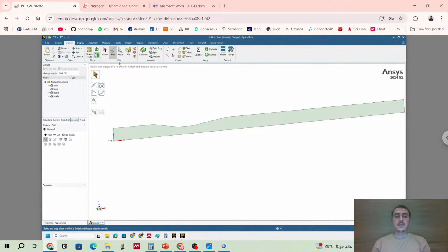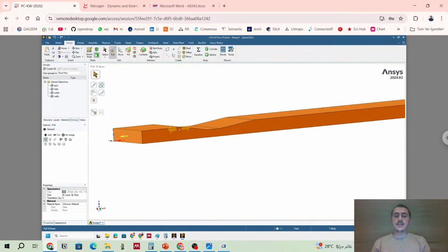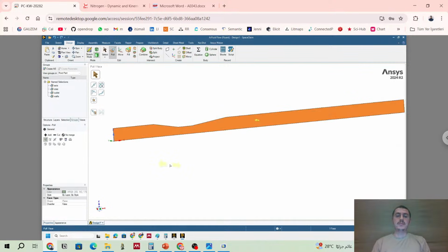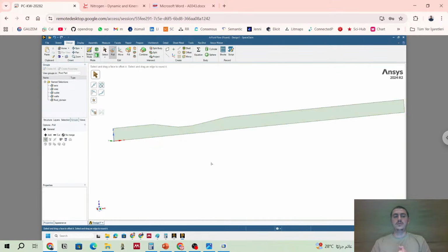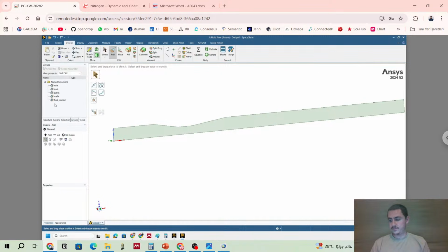So I define the walls, then I will click inside of the surface, and sometimes if it's a 3D, let me show. If it's a 3D geometry, so you triple click to name the whole entire 3D as a fluid domain. But now let me Control Z. My fluid domain is only a surface, so I will name my surface as fluid domain. Okay, now we have a lot of things we made. We draw the geometry, we named the boundaries, we are ready to close.